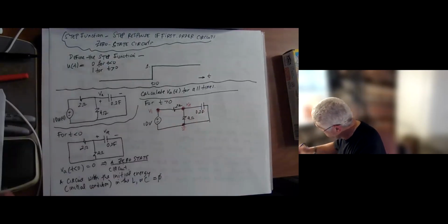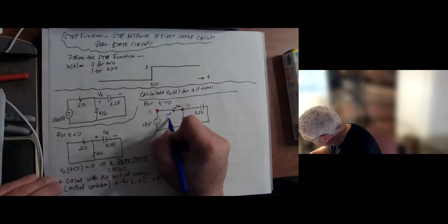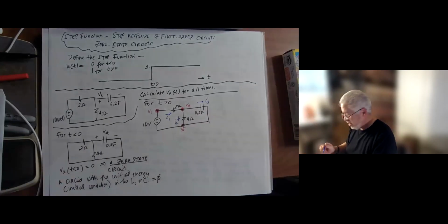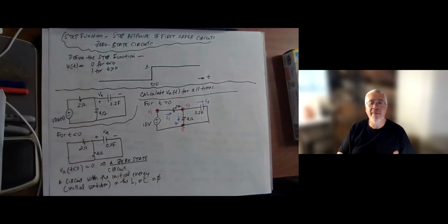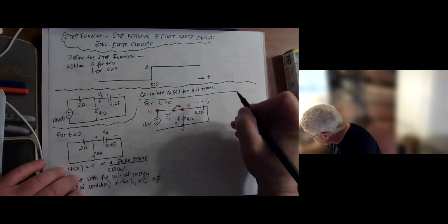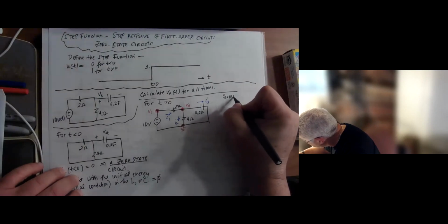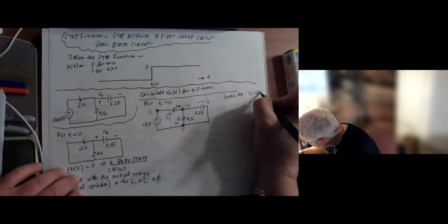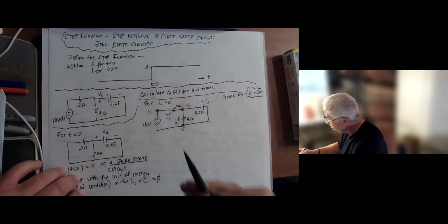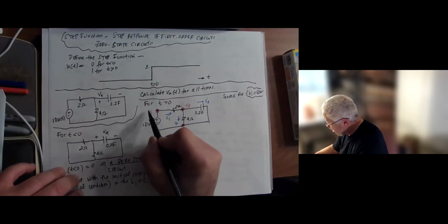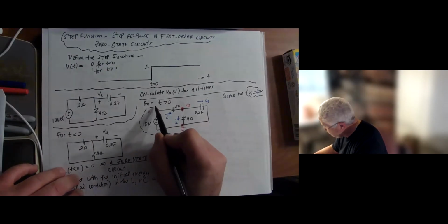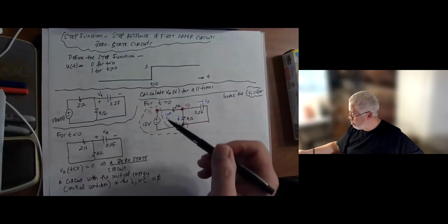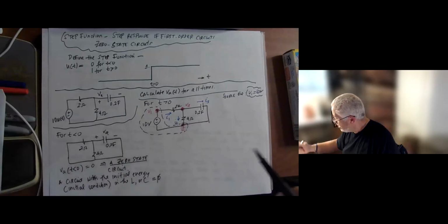And then furthermore, I'm going to put currents on my passive elements: I1, I2, I3. So that's setting up in a typical nodal approach here, and the source equation here. I'm going to say V1 is 10 volt. That's pretty simple here. The reference node is here. I also have a super node, but I won't do much about it because it has the reference node. So that's my super node, but the source equation for the voltage source is 10 volt.